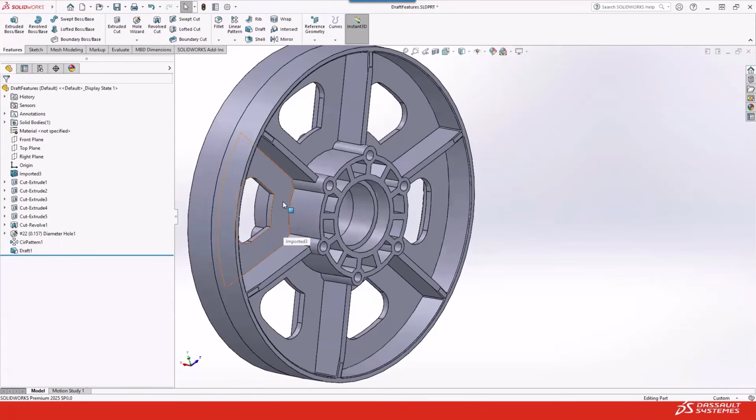And why is that? If I choose this as my neutral plane, everything as I move away from it gets narrower on this side. But everything on the other side would get wider if the neutral plane was reversed. So if I used this all-in-one feature and I tried to go in 2 separate directions, it wouldn't work. I'd get narrower on one side, wider on the other.